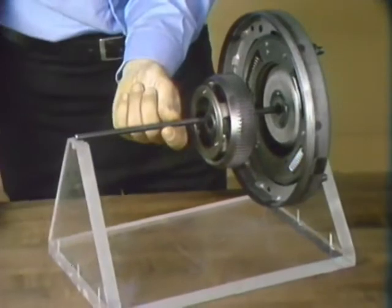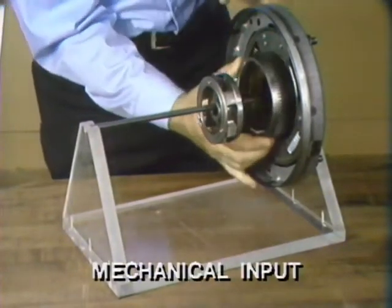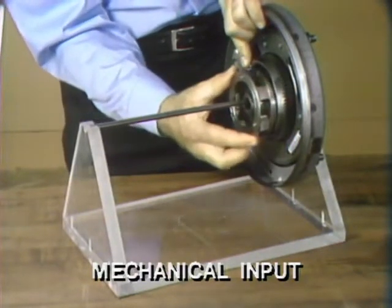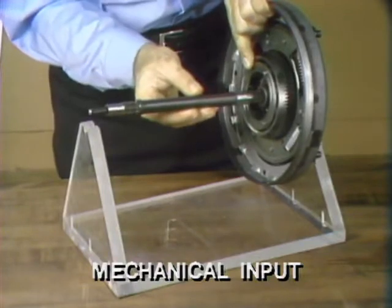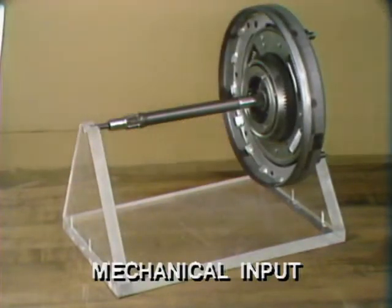Let's put the parts together as they are involved in power flow. For mechanical input, we start at the damper in the converter cover. The splitter planetary ring gear slips into the damper splines, so the ring gear will always turn with the converter cover at engine speed. Now the planet carrier assembly fits inside the ring gear so that the pinion gears mesh in the ring gear. And now the intermediate input shaft is splined into the planet carrier so that it always turns at the same speed as the carrier.